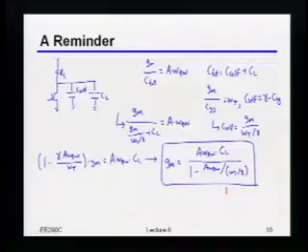So this is basically telling you that no matter how much GM you spend, if you try to get higher bandwidth than the intrinsic bandwidth of the device, it's not going to happen. Not only that, depending upon how close to that intrinsic bandwidth you're operating, it tells you exactly how much extra power you have to spend because the device doesn't have infinite bandwidth. In particular, how close to the intrinsic bandwidth of the device do I have to be in order to spend 2 times what I fundamentally would have had to spend anyway with a perfect device?